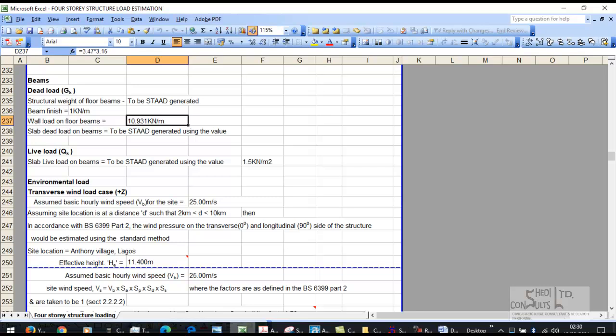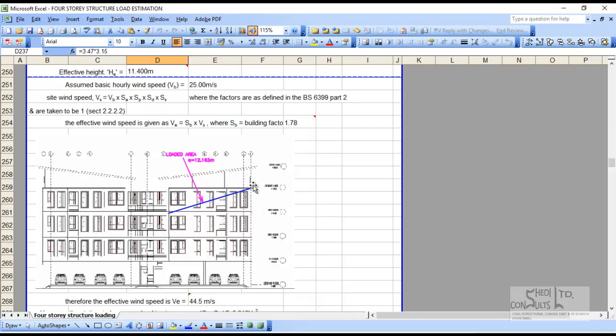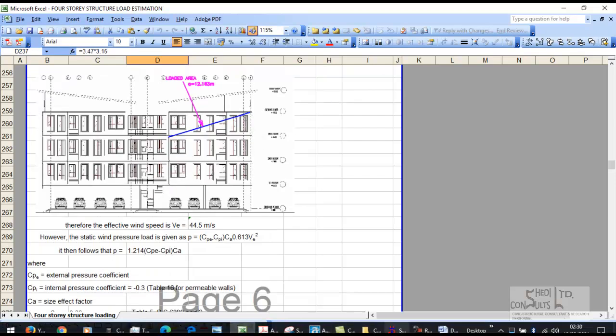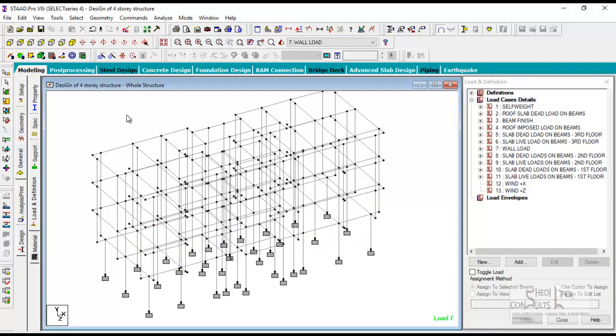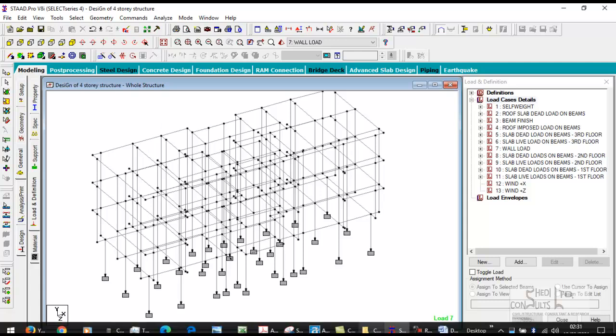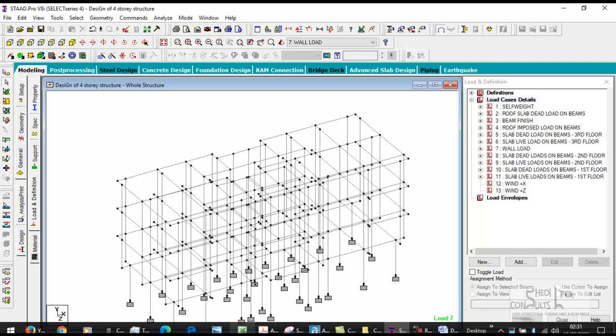In the X direction, we had calculated the wind loads. Look at that. So X is the longitudinal direction, which is 90 degrees. In the transverse direction, it's treated as 0 degrees in the code of practice. So note that. Wind in the transverse direction is the wind load in the Z direction, and the transverse direction is catered for as 0 degrees.